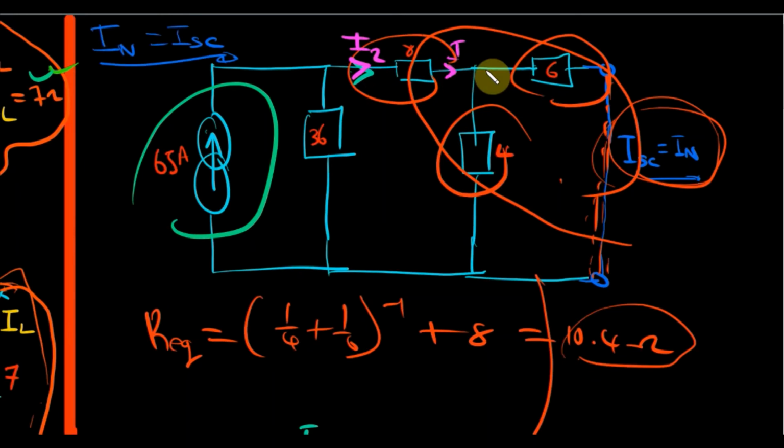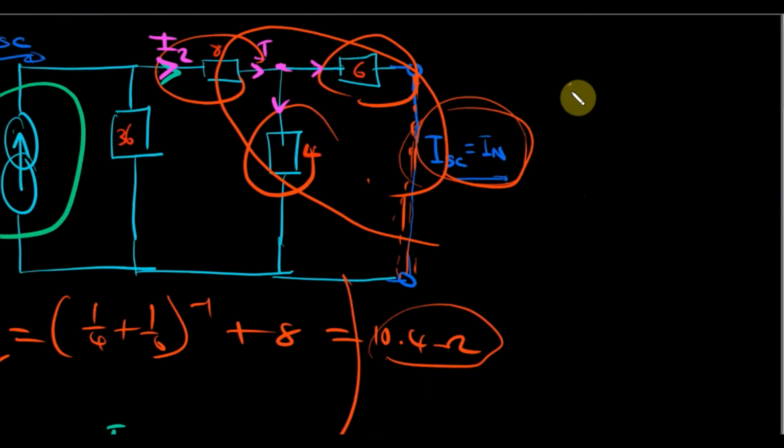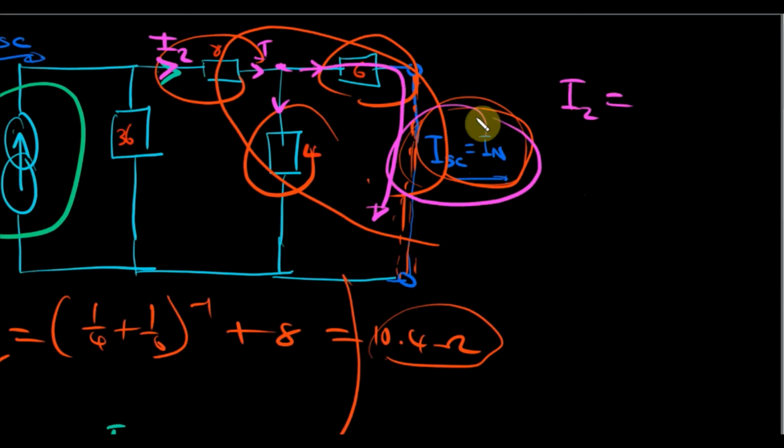As it arrives at what we'll call junction 2, you will observe that it divides again. There's current division here, so we need to do current division twice. I2 becomes our source current here, and let's call the current passing through the 6 ohm resistor our short circuit current, which is the current of our interest.